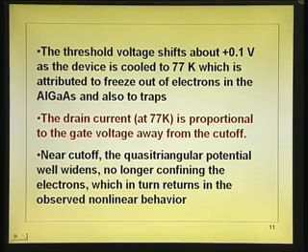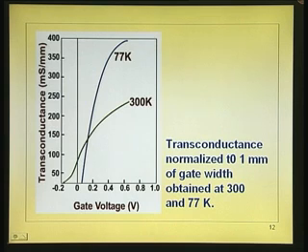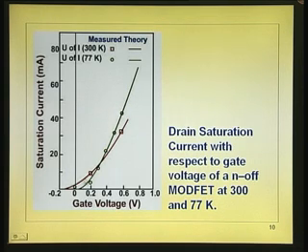The current is proportional to gate voltage away from the cutoff. Near cutoff, instead of linear, actually the well widens and you get a much more nonlinear response. See, what the statement means is, you get the regular square law characteristic, but here you have got much more nonlinearity, because as you go nearer to the off state, what happens?